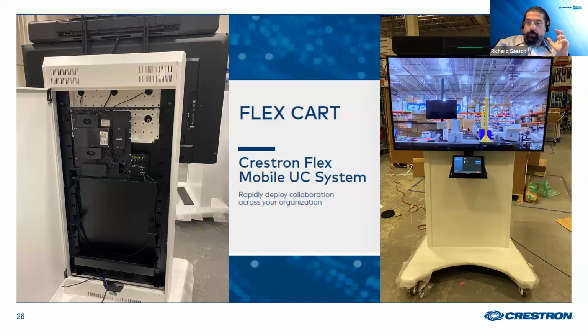Ethernet is required because this is a UC engine. Wireless touchscreen control is not supported as it is, again, a UC engine. Same thing for other UC engines. They do require the hardwired TSW panels. Screen weight limits will be discussed on the specs on the website.